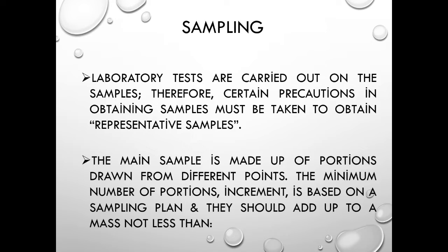And laboratory tests are carried out on samples of the aggregates submitted. So in other words, are these aggregates representative of the aggregates in the pit? In other words, these samples, were they taken in such a way or such a procedure to ensure that they are representative? Sampling is equally as important as the lab testing. If the aggregates aren't sampled properly, they are misleading. So in other words, the aggregates may be rejected from use in concrete.